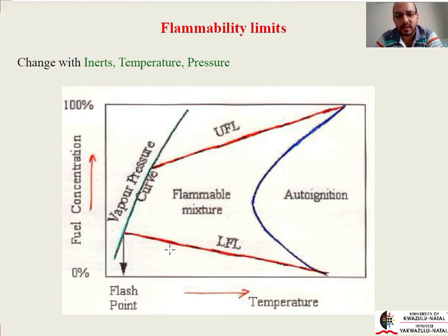On the other hand, we have the lower flammability limit, and this is a case where the fuel concentration is so low relative to the amount of oxygen that your fuel molecules are actually quite highly dispersed. Okay? And because they are highly dispersed, even if you try with an ignition source, you try and light a match there, it would just be 1 second of burning and that's it. There won't be enough molecules to continue the combustion reaction. Remember, the combustion reaction is a propagating reaction. Okay, it's not just one sudden explosion.